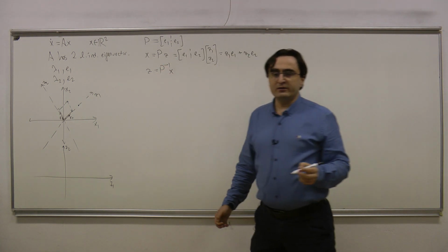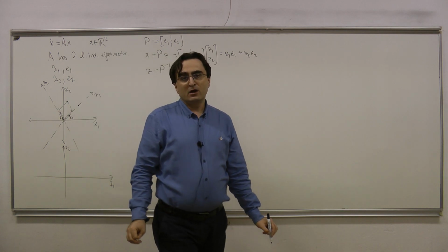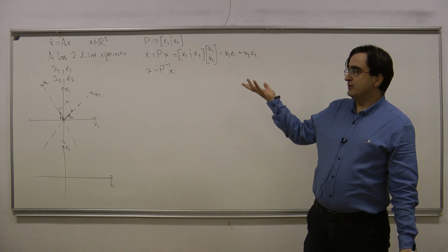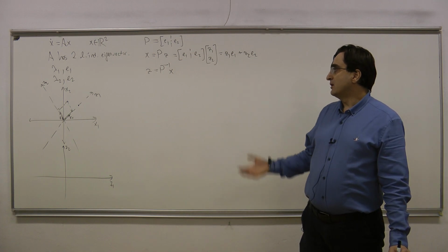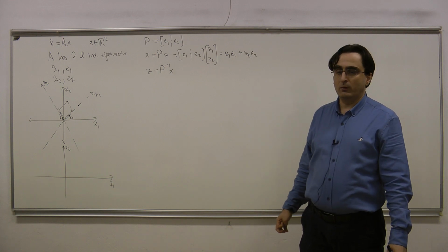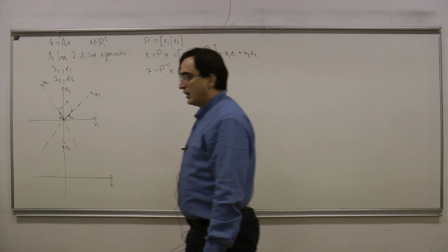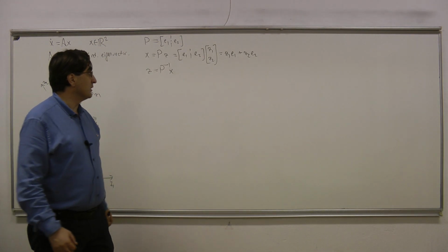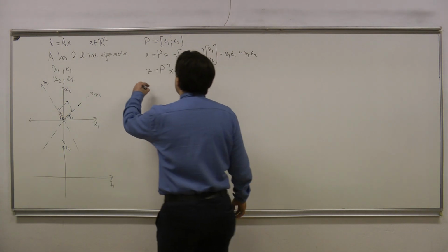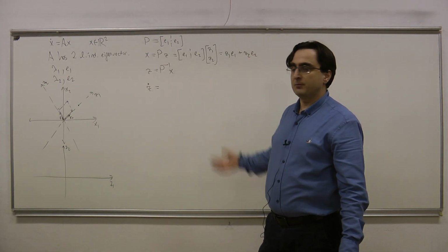So now I can obtain the new system dynamics in my new state coordinates. We have seen in the last lecture that when I obtain the new state dynamics, this new A matrix would be in a very simple form. Actually it would be a diagonal matrix, and the diagonal elements would be the eigenvalues of the A matrix. Let us see what we did so far. So I would like to calculate z dot in terms of some matrix times z.